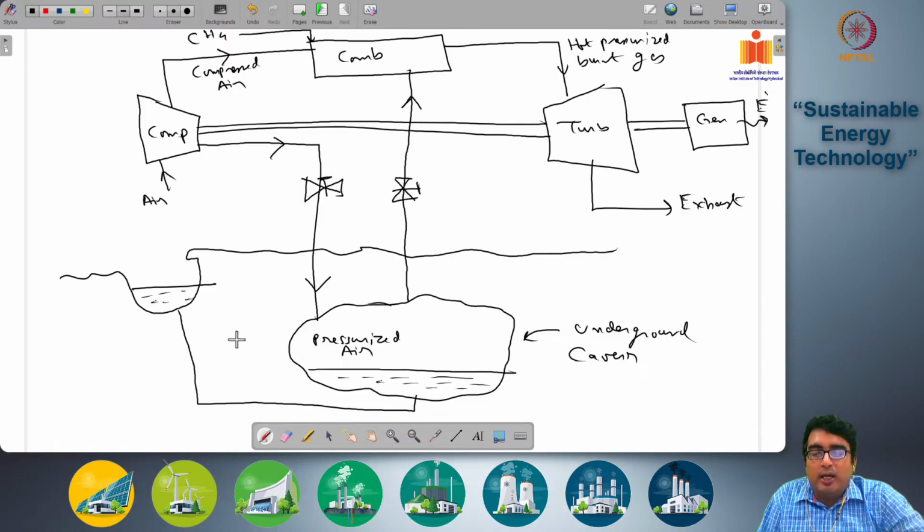Okay. Now this water system helps to keep the pressure of this air at a constant level. So as the amount of air increases, the water is pushed back out of the system and is going into the water system here. So that's how the pressure is being kept at a constant value in this location. And when air is being taken out of the system, the amount of air is decreasing, then what will happen? Typically the pressure will decrease, correct? But here what happens, the water level increases to occupy that empty space taken out due to the air, and the pressure is being held constant.